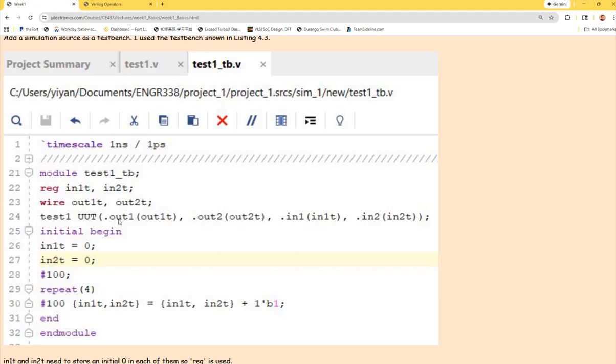Keep in mind that the module name has to match whatever is being instantiated in the top, and has to be half underscore adder, in lowercase. That's the name of it. So for your module names, if you have a different module name, or you use a dash instead of an underscore, or if you use uppercase, it won't work. I'm going to deduct points, so make sure you use the correct names. You know what I'm saying? Now we are working on problem number 7. Make sure you have the correct port names and correct module names.